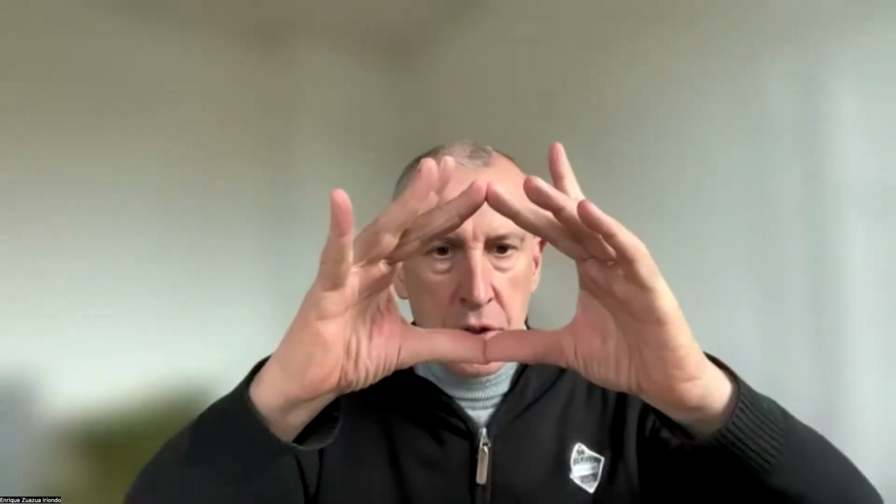Yet you need to fine-tune your finite element method, and you reach the conclusion that in order to have this property, you need the triangles of your finite element mesh to be not too far from equilateral triangles. If there is too much eccentricity in the triangles, this property is lost. So you see the giant gap between the kind of, despite decades of numerical analysis, right?